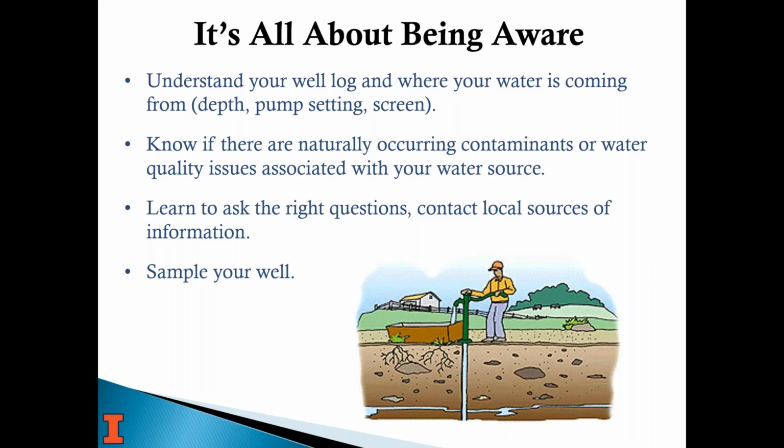So we recommend you test for those annually because if you have elevated nitrate or you have coliform bacteria, that means there's likely a pathway into your well from near the surface. But if someone samples your well for coliform and nitrate and you don't have either, that does not mean your water's safe to drink necessarily. I mentioned arsenic earlier.